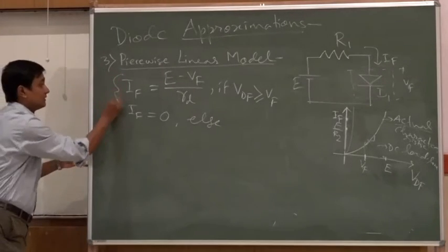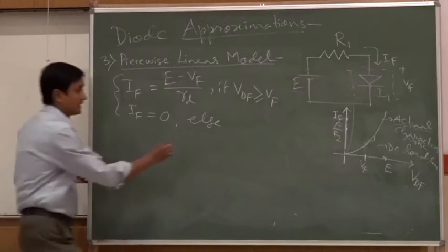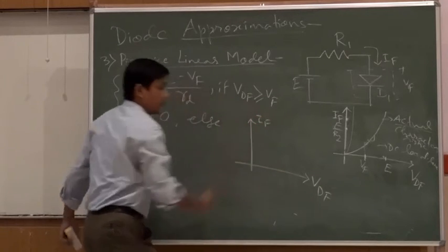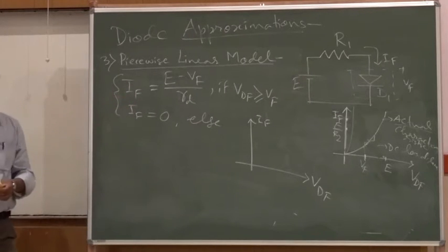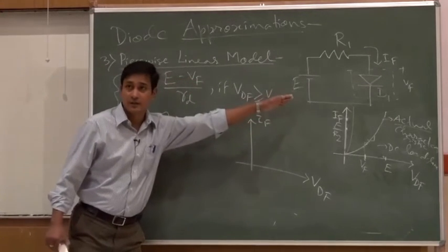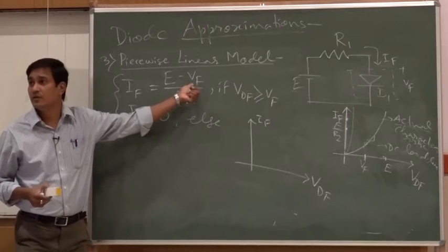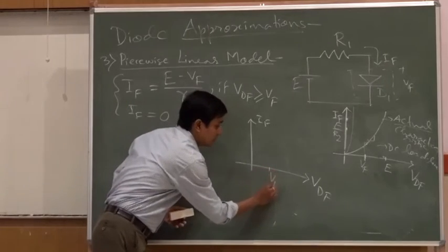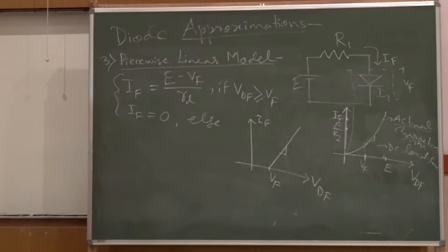Mathematically I could represent the model. Now I want it graphically to represent that same way we were doing in the earlier case. If this is the scenario, I am seeing here, if only one resistor would be there and Vf would be 0, then it would be a linear curve with a slope 1 by Rd. But here the origin has got shifted to the Vf value. So it is one straight line, but it has started from Vf with a slope. How is the slope decided?